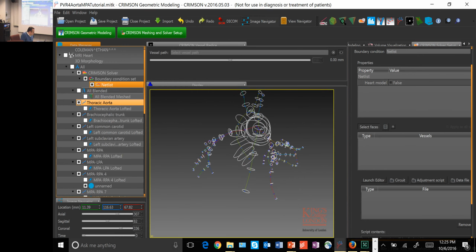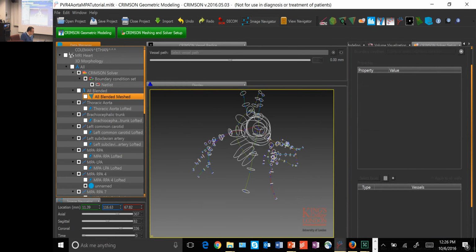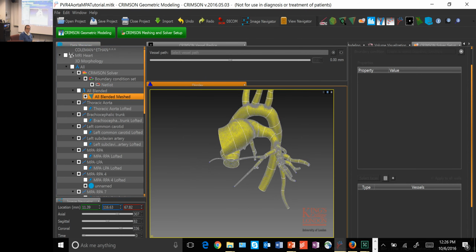We can take care of basically all the modeling tasks, including mesh generation. So this is the finite element mesh. And all the boundary condition specification is actually done on the analytical model, not on the mesh. Because when we go through the modeling process, we do a lot of mesh refinement. And fundamentally, the boundary conditions belong to a model, to a conceptual phase, and not to a specific mesh. So this is another practical reason why having an analytical model is a good idea.